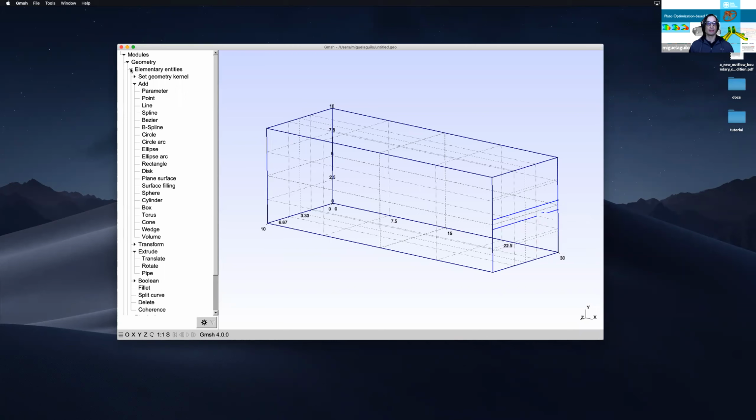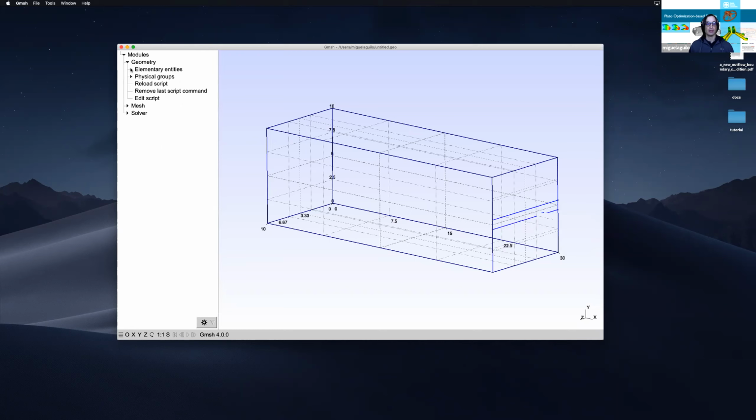So next, now that we have our bounding box, it's fairly easy to then mesh the geometry using Gmsh. So with Gmsh, there's 3 steps that you need to follow to mesh your geometry. Basically, the first thing that it does is it applies the seeds on your lines.